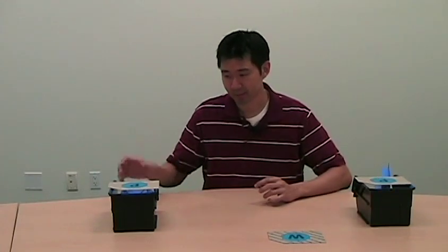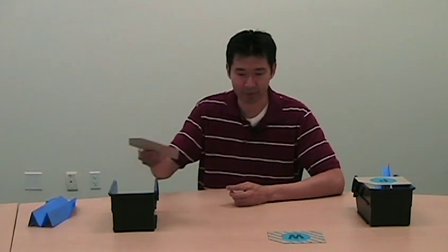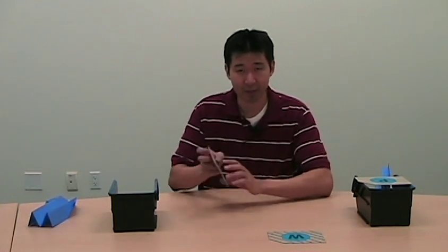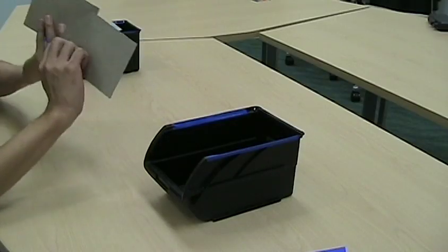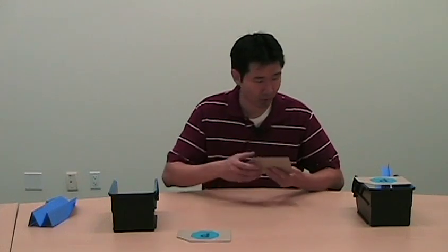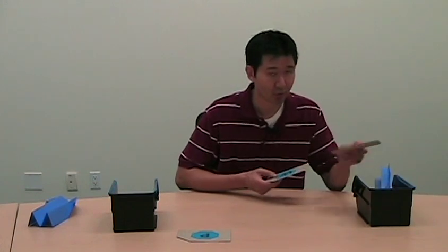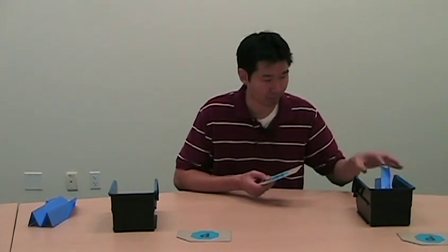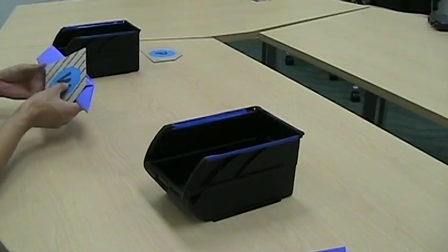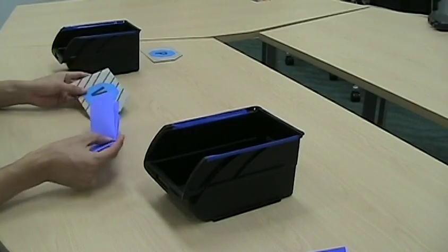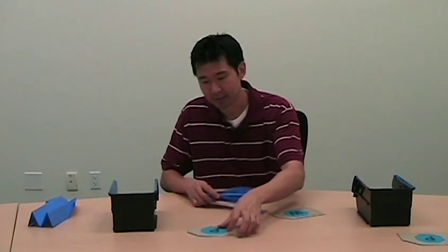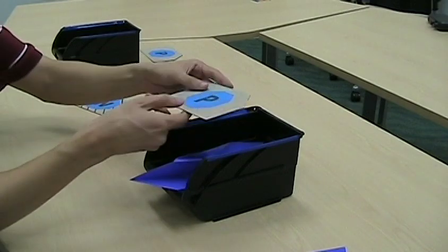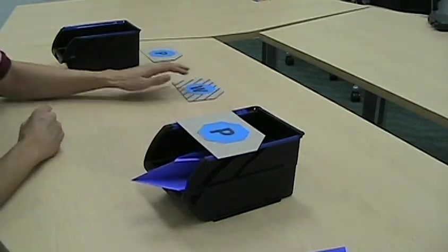So, when the next workstation decides they need to pull this plane, they drop off this P card to me. I see the P card. I look at what I need to withdraw to produce this plane that they just pulled, and it's this W card. So, I walk over to the previous area, drop off their P card, so they in turn produce what I just took. Walk back over to my station, and confirm that it is the blue plane. I finish off the plane, take it to the supermarket, and drop off the P card there. So the system resets and it works in a loop just like that.